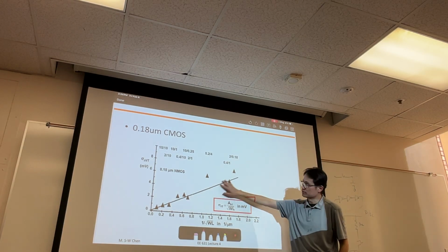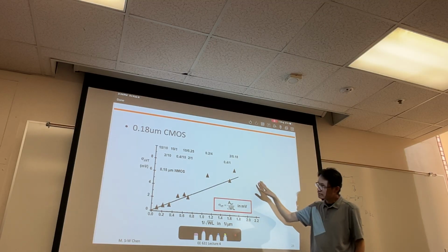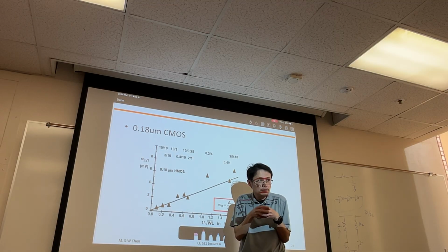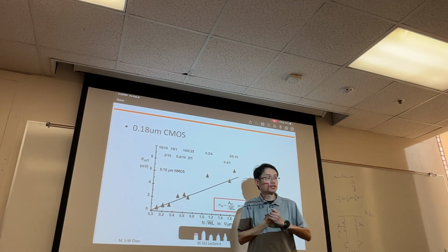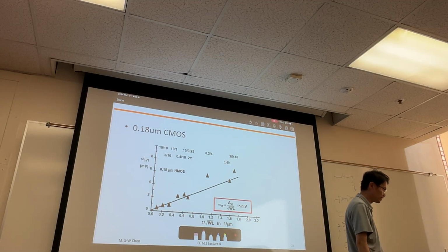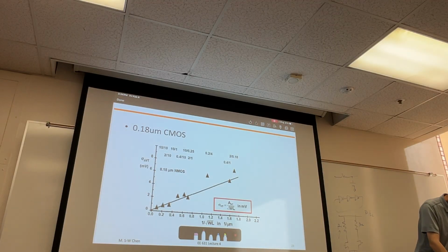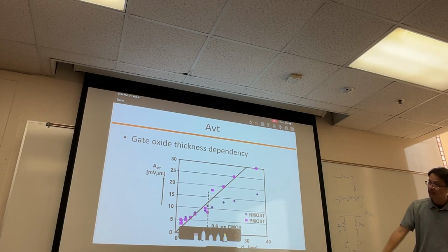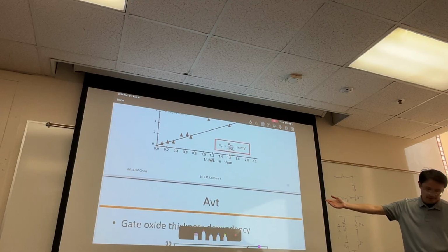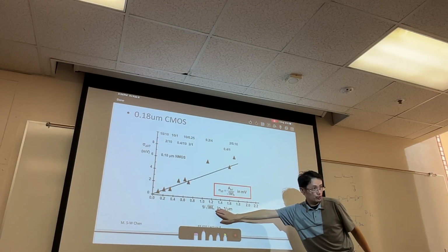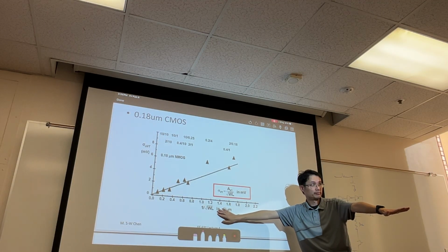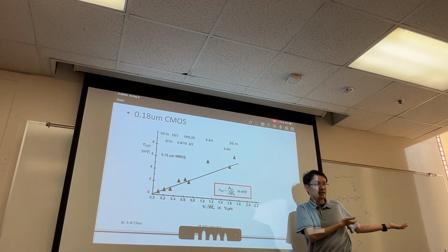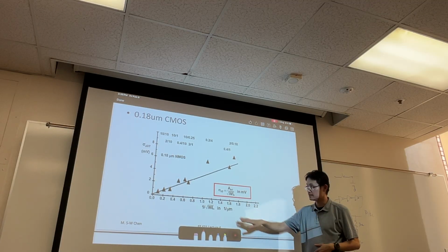So all this trend, basically you can see this standard deviation, right? If the area you consider is small, you expect more threshold voltage deviation when you do the matching. Then it just comes down to the A_VT factor, right? So we understand, when you design, this is what we can control, because you control the size of the transistor. Make sense? You and I do not control the doping or whatever. That's determined by the process engineer, right? But what we can decide is this.